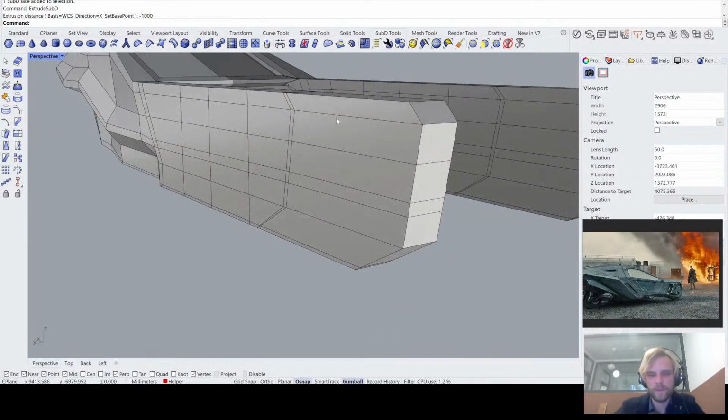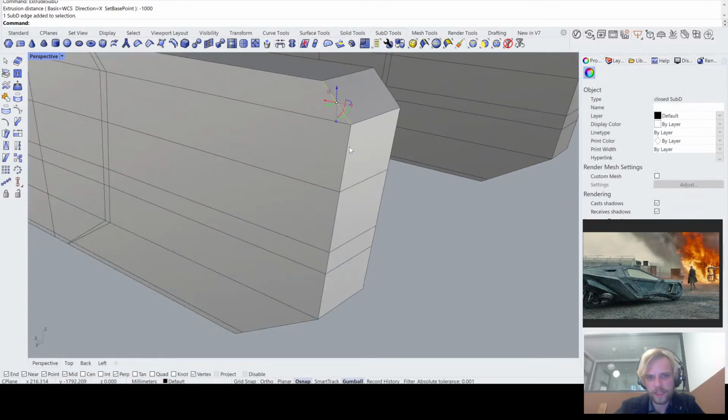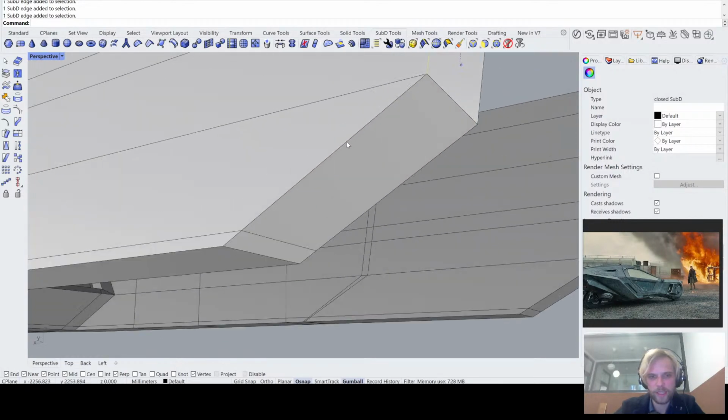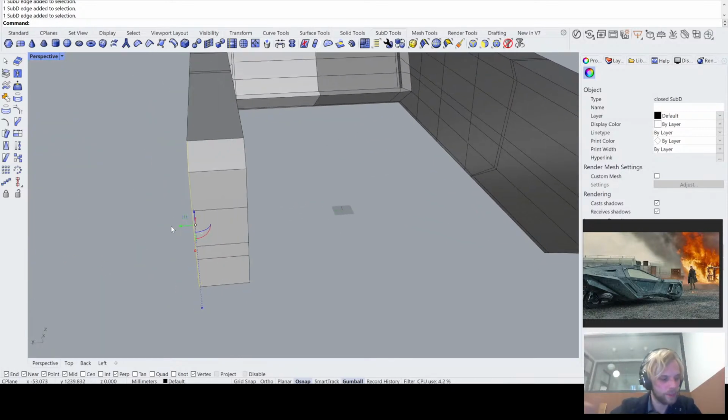Like that. And then what if I would select these edges right here? Because this is simple. I just want these edges, right? These edges right here, just to be offset to the side by, this is in millimeters, so a centimeter, -10.